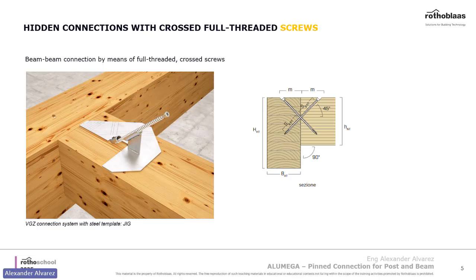These inclined screws give you a huge amount of capacity because of the withdrawal forces and also the shear forces of the screws. They're very simple and easy. If you have a slot, you can easily just drill them at 45 degrees. You don't have to measure it by eye.